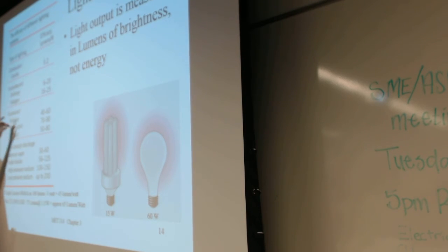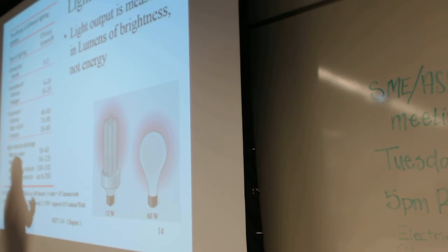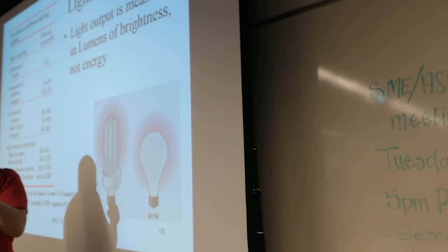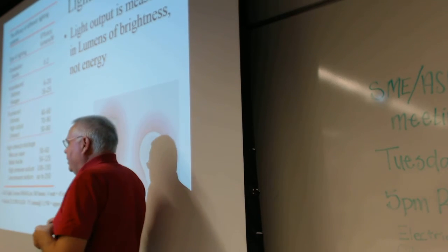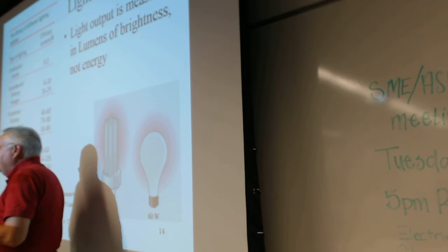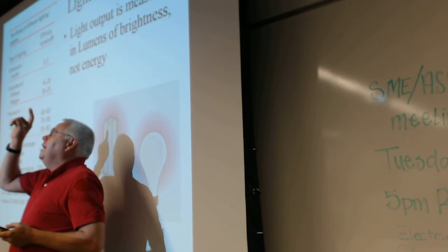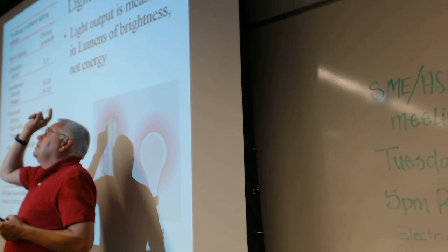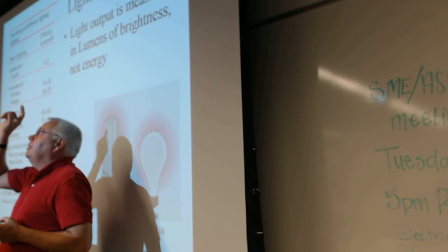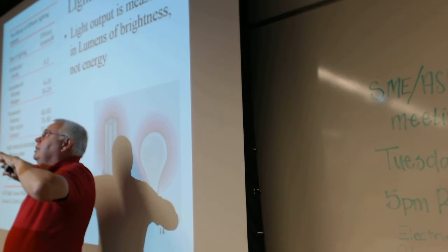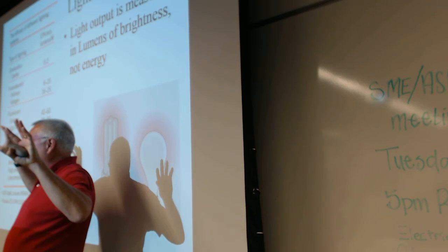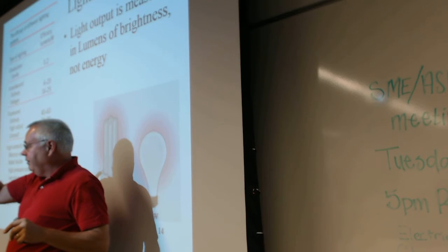Fluorescent is different. These are all about a filament that glows to some temperature and gets hot. Fluorescent, actually, it's electrons hitting something that fluoresces. It's like glow in the dark. Isn't there a different gas in it that glows when you hit it with an electrical charge? Yeah, the electricity goes through the gas because it's conductive, and it generates electrons that hit the surface, and it's really the surface of the glass that has a fluorescent coating on it.